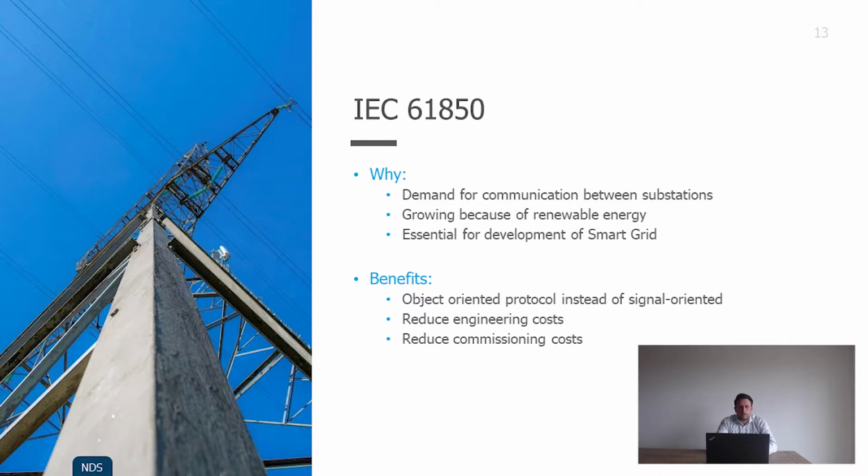Well, the IEC 61850 standard was designed from scratch and with Ethernet as the communication backbone, making use of modern technologies just like VLANs and priority flags for GOOSE messages and SMV sampled measured values.